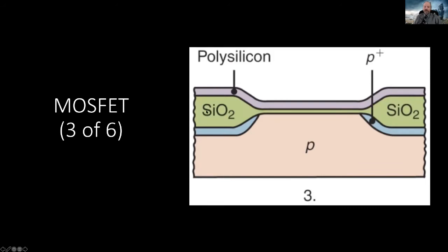The green region is now a silicon dioxide. So we grow silicon dioxide again, okay? And then we put polycrystalline silicon down, okay? So in between the previous step and this step, we've stripped off the silicon nitride and then the silicon oxide we put down at first. Okay, now the polysilicon, okay, is going to be a conductor. Okay, so now we've deposited the polysilicon.